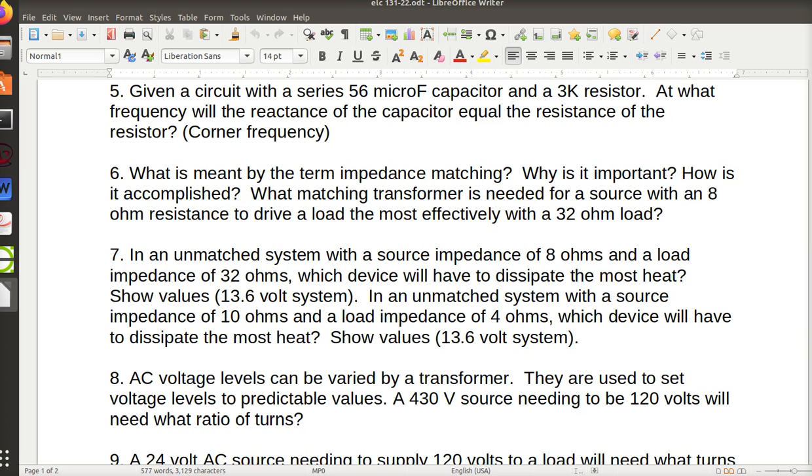Well, your amplifier has an impedance and your speakers have an impedance, and one of the things that you can do with a transformer is transform the impedances, if you've got the right transformer, so that the source and the load impedances match, and then when you do that you get the most power out. You also do that in broadcasting with an antenna. You have to impedance match.